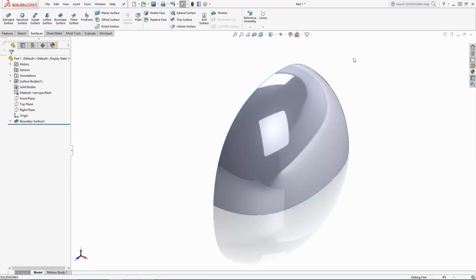This is a nice feature in the boundary tool that allows you to create organic forms without the need for guide curves as you would need when using the loft tool. We just need to model half of the tiara, and we'll just mirror that half later on to wrap up the design. So this will be my base surface that we can create various extrusions off of.